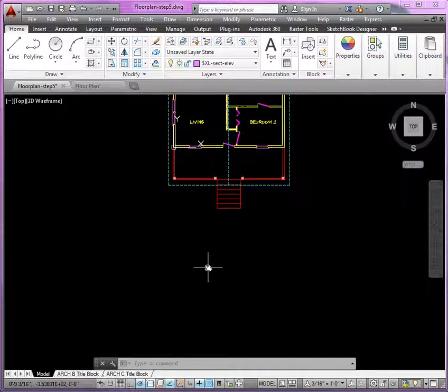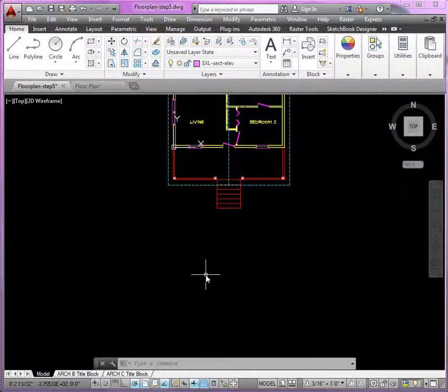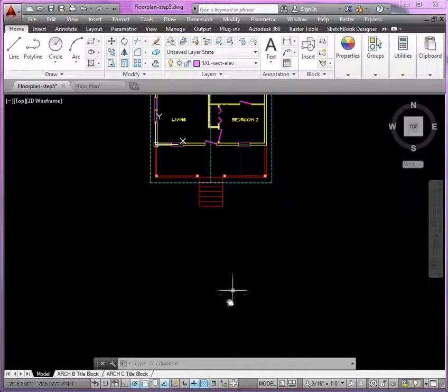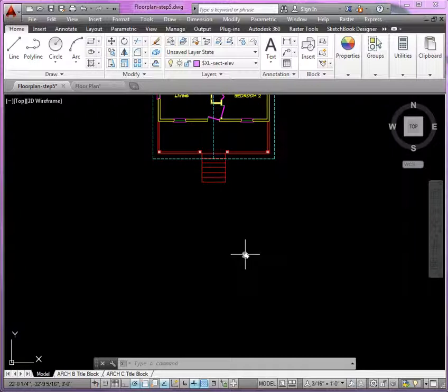All right. I would suggest that you have a layer that's just for your construction lines in elevation. And I would also suggest that you use the same layers that you have for your floor plan to represent the same elements in elevation. So first, what I would do is set up all the reference lines. Now, some distance away, this is totally arbitrary, start with some horizontal lines.